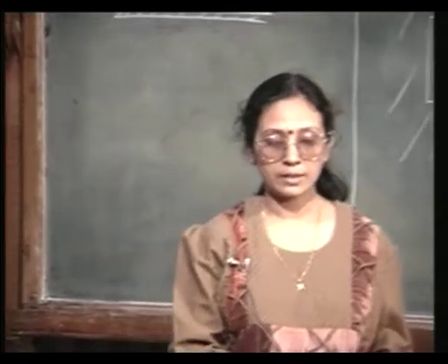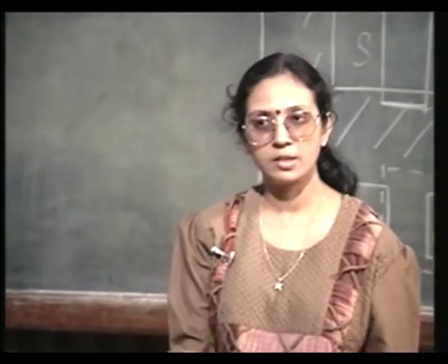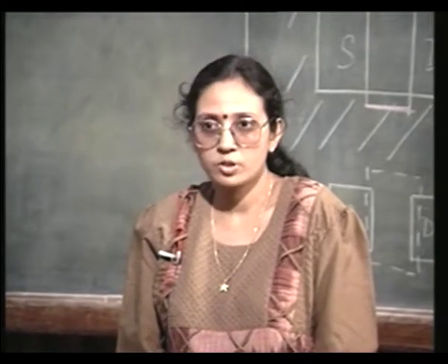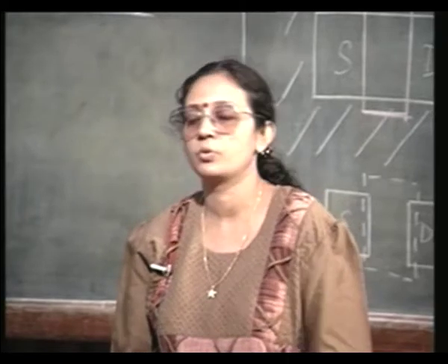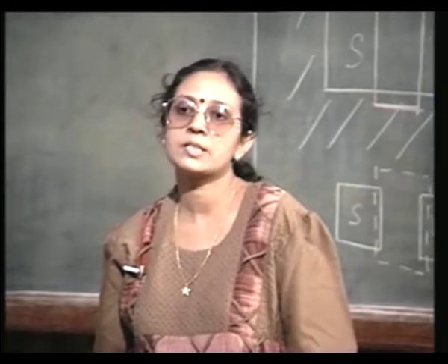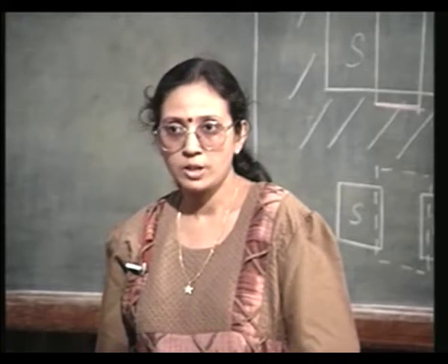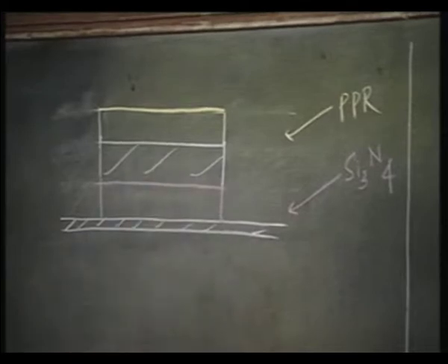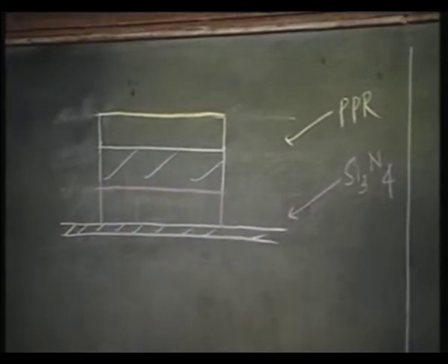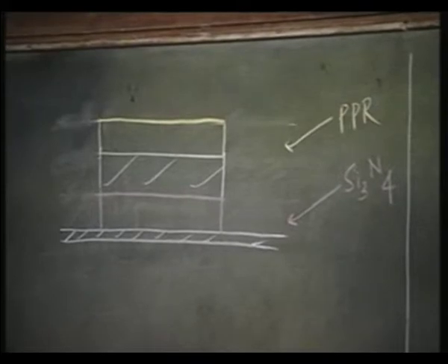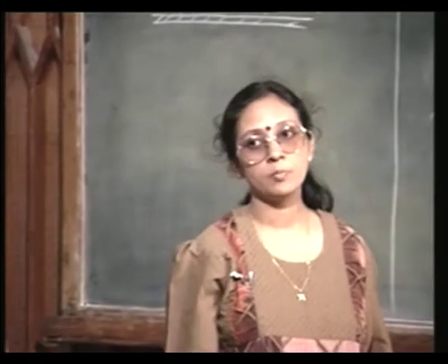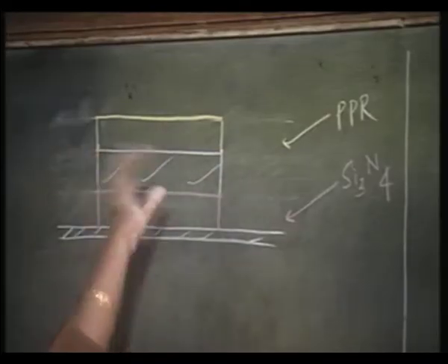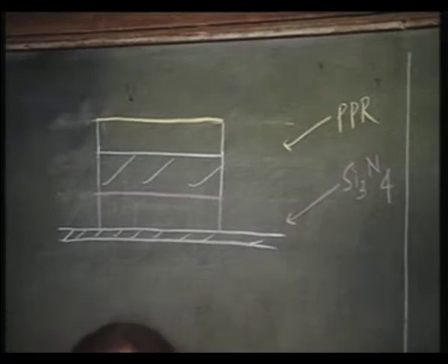Okay. So, actually that is the reason why we needed to put this CVD silicon dioxide. You see, if you just have silicon nitride and then tried to protect it with positive photoresist, the positive photoresist cannot withstand orthophosphoric acid. So, in order to protect this silicon nitride layer, I must have a silicon dioxide on top. Okay. Silicon dioxide will withstand positive photoresist. Silicon dioxide will withstand orthophosphoric acid. Of course, this top layer will get destroyed when you are putting it in orthophosphoric acid.